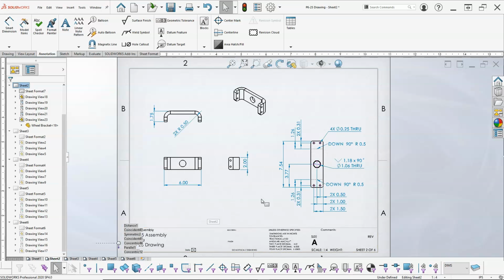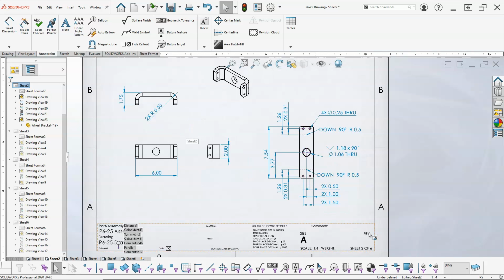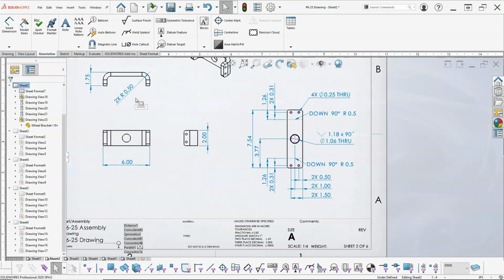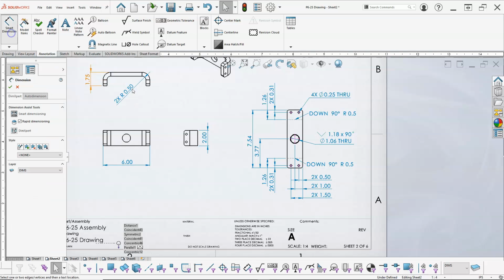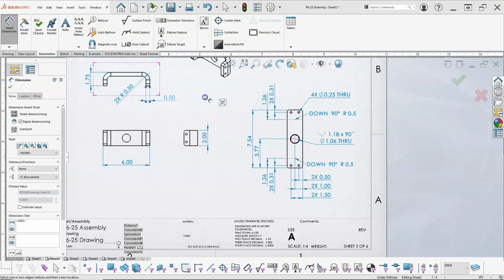I went in and we had done the flat pattern. Put most of the dimensions on the flat pattern because that's pretty much the focus of the manufacturing. Alright, so one of the things with the view is the finished product I would like to have at these dimensions with a generous enough tolerance that they're not going to be too difficult. Now the real problem here is this is going to need a really heavy press brake to make that material, and I did not call out the material, so somewhere in here looks like a good spot. We have 1/2 inch material.